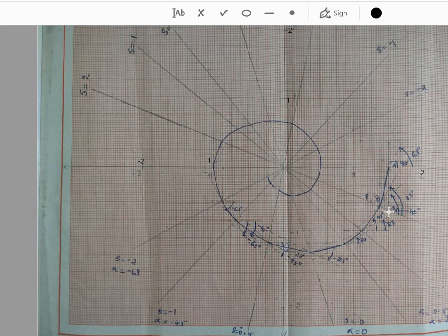So here you got 2 points. One is the extension of plus 90 degree and the other is the extension of plus 63 degree. Now find the midpoint of this line segment. That midpoint will be the path of the phase trajectory. So the initial point is A and the path of the phase trajectory at the next isoplane is B. That is the midpoint of plus 63 and plus 90 degree.